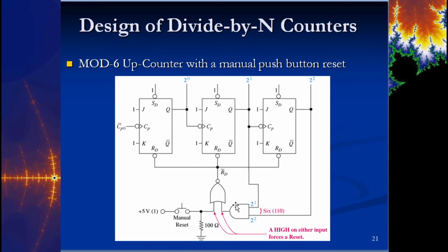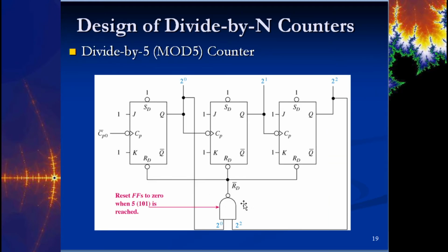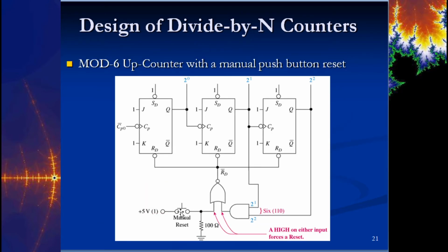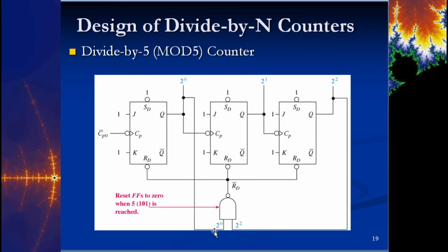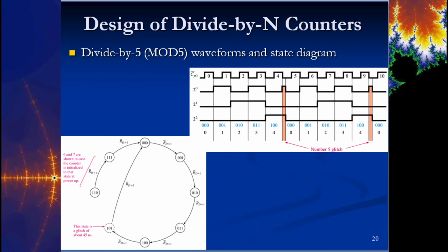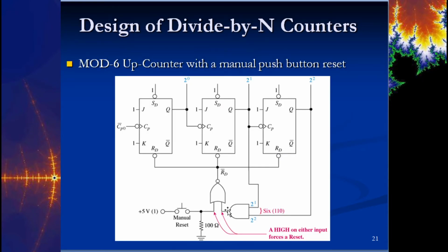Whether it's a straight reset like this, or you have the option to do something else, the final logic here is an OR situation because you want this or this. But here, like I said, you want the AND operation. It's just that you have to use a NAND because you have to account for the active low. So here, we're not accounting for the active low because it's going to be either this one or this one that gets it done.